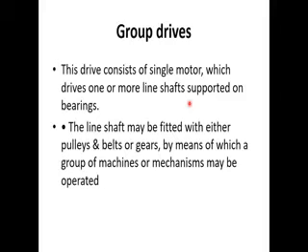The advantage of group drive is that one motor is used to control n number of machines, so the initial cost is very low. And the drawback of the group drive system is that if any problem occurs in the motor, it will collapse the entire system. That is the main drawback of group drive.